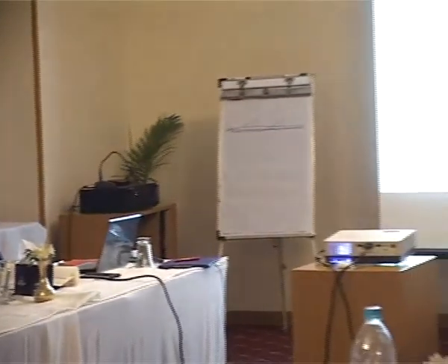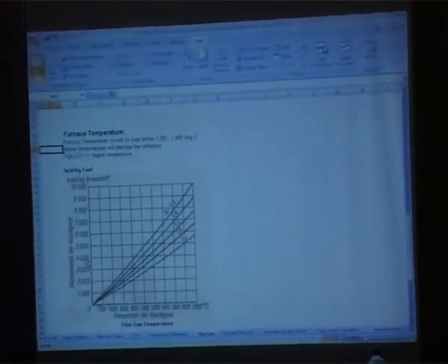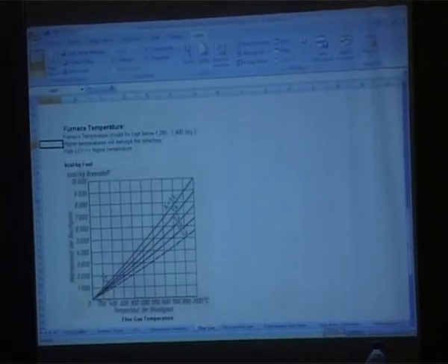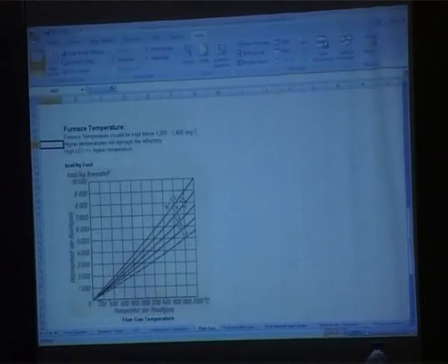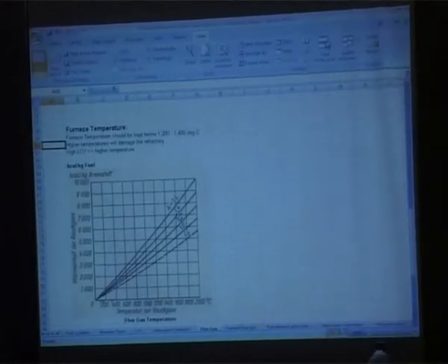This here, kilocalories per kilogram fuel, that's over here. And when we talk about biomass, we are in the range here 3,000 to 4,000 kilocalories. And then we have the flue gas temperature. Depending on this here is surplus lambda value, is air surplus. And with biomass, we would typically be here